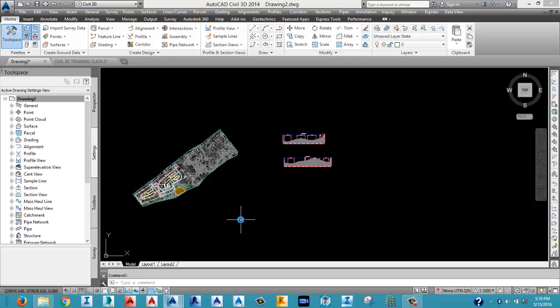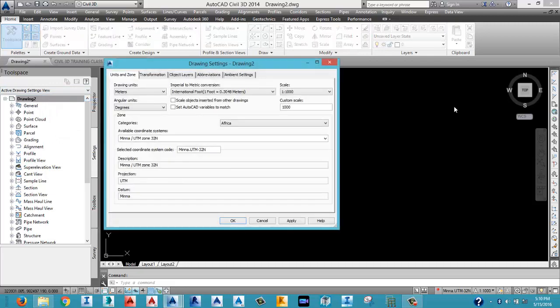Is it because you're connected to the internet? Everybody's going to MINNA? No, mine is not connected now. The internet is not working again. So how was the MINNA? No, it will come there automatically itself. You pick Nigeria. On the datum database of this program, they've already programmed all this. It's in the software already. Why MINNA? That's the reference datum of Nigeria, the national datum, Niger State. You always use it; if you see the drop down, go there again. Go check your drop down.